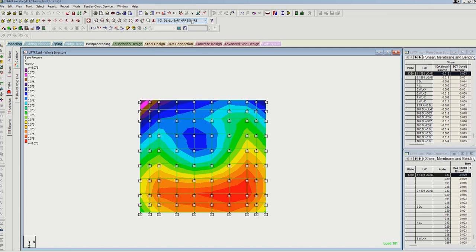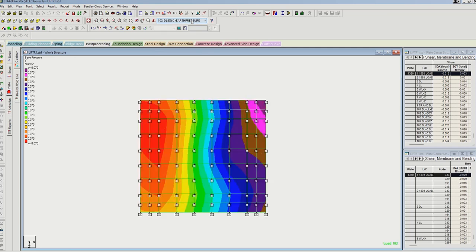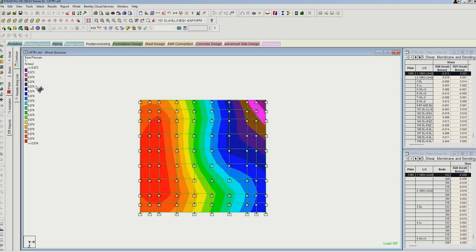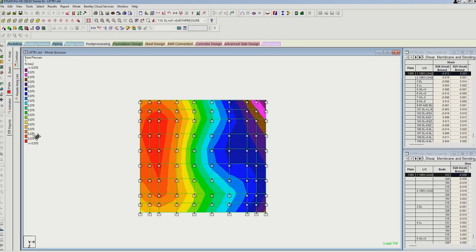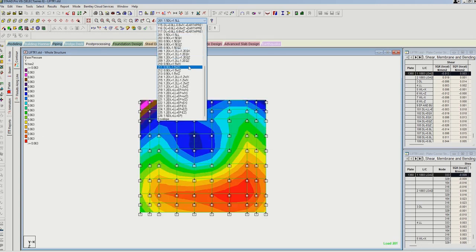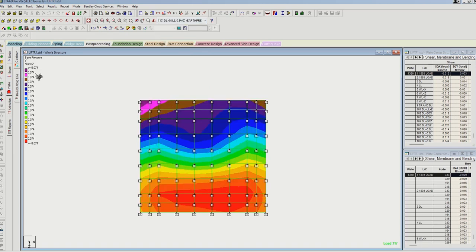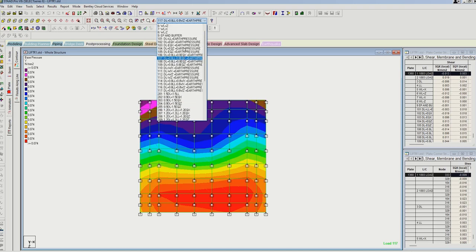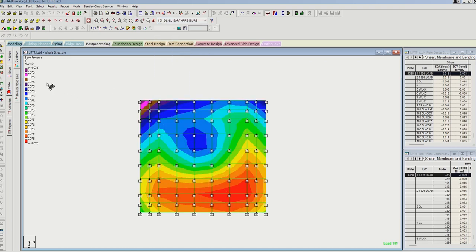And if I keep on changing the load combination, it is 70, you can see from here, and here this load combination is changing, 73, 74, so we can see for the service load combination the maximum base pressure that was coming is 75 kilonewton per meter square for this load combination, dead load, live load and earth pressure, which is less than 90 kilonewton per meter square.